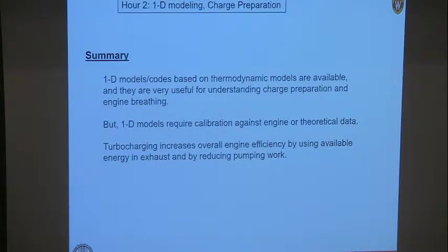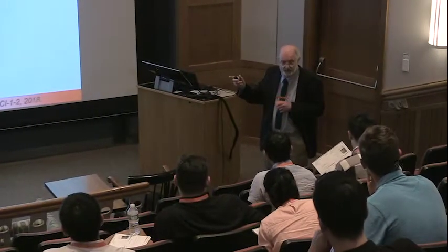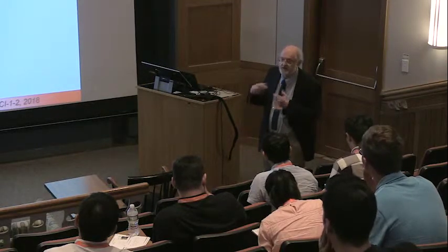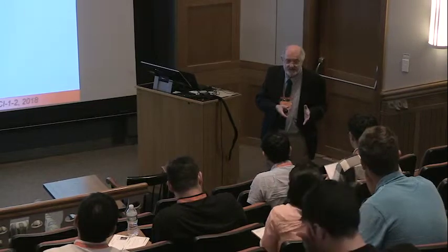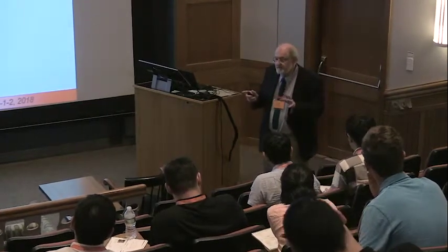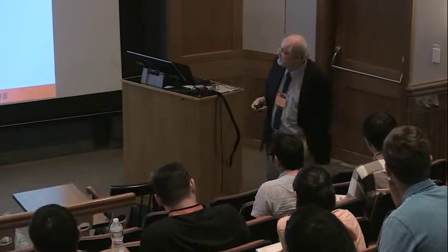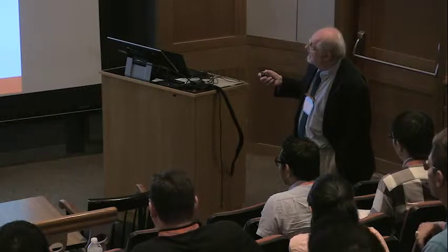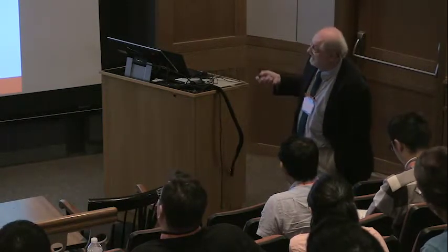And that's what we're going to talk about as we move on. But for now, all that they say is they assume that you have a certain pressure at the exit of the exhaust system that's driving the turbine, and you're going to use that to then boost the inlet. But how you're going to use those two bits of information really relies on understanding what happens in the combustion chamber. So these 1D models are very useful for understanding charge preparation and engine breathing, and in fact, they're essential for understanding that.